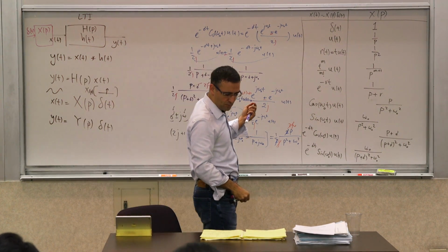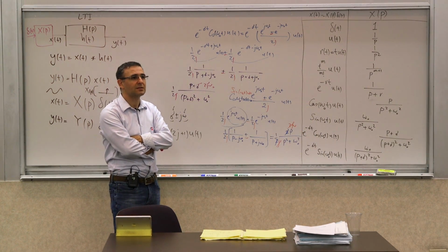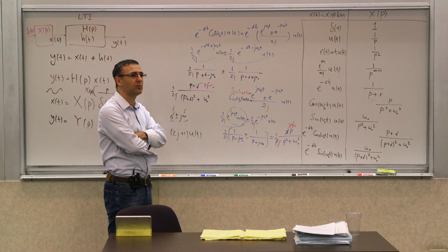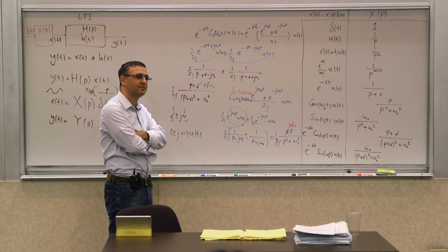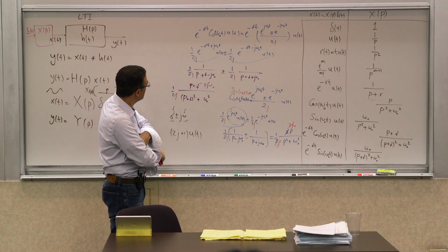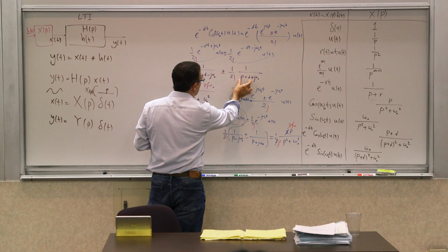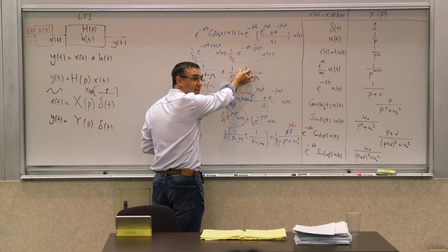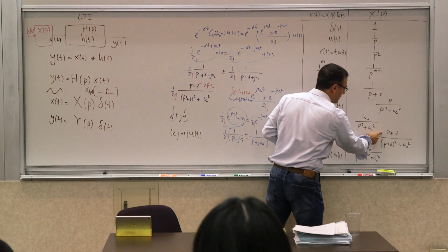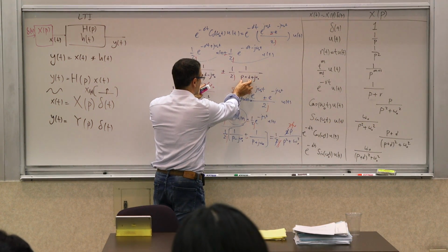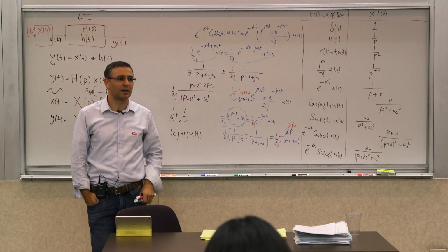So you have this. Now, what is important about these, if you think about them? Look at these waveforms and tell me what's important about them. You have a question? Shouldn't there be a 1/2 times the cosine one? No, why should there be a 1/2? Because it's just p plus sigma. Right, but remember, when you add them, there's a p plus sigma here and there's a p plus sigma here. So you have two p plus sigmas, and there's a 1/2 here. So the question is that shouldn't there be a 2 here? But the answer is no, because you get two p plus sigmas and you have a 2 in the denominator. The same thing with the omega. You get 2j omega now, and the 2's cancel.